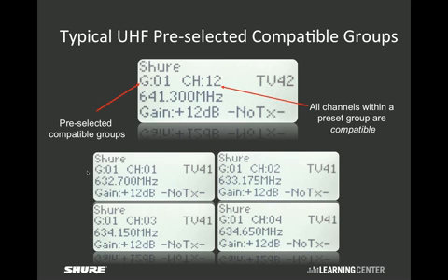Now, would this work, Gino, if I wanted to add like 5 of these systems to an existing set of wireless gear already that might be a different brand or a different model? Well, no, because then you have to consider the frequencies that those things are tuned to or can tune to, and those will impact the frequencies you choose here. So again, you'd need to come back to an overall plan using something like Wireless Workbench.